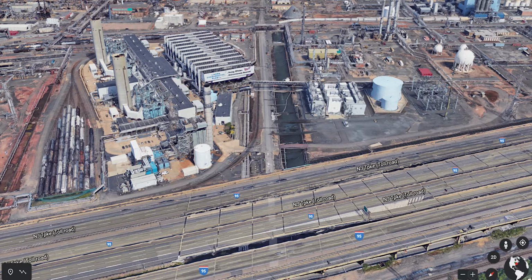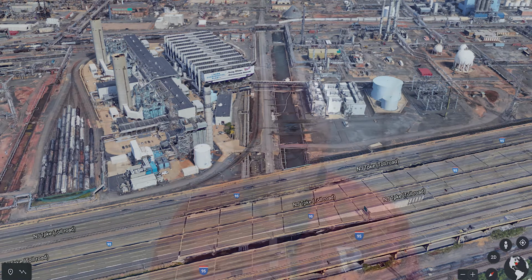The reason a dry cooling tower was installed was because when you have a wet cooling tower where you're using evaporative cooling, the water evaporates and generates warm and very wet air leaving the cooling tower to go into the cold atmosphere, and it often tends to condense. This plant happens to be upwind of the New Jersey Turnpike, meaning that if they had used a wet cooling tower, every morning there would have been a dense fog covering the turnpike with an ensuing carnage due to poor visibility. Of course, this is a very specific case.